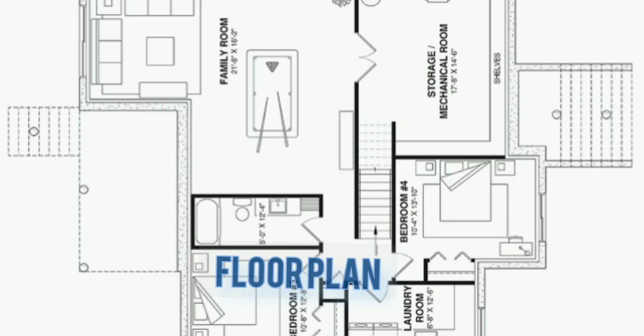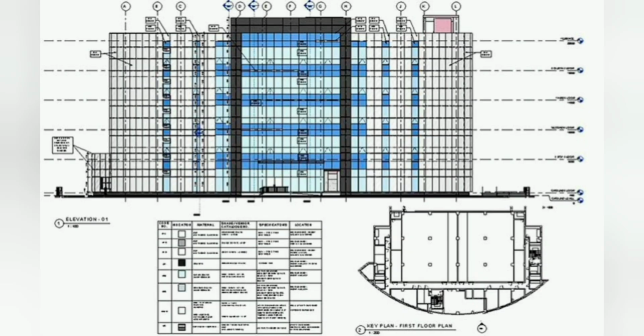These are your primary guide for room layouts, door and window locations, and wall types. Pay extreme attention to the dimensions. Are they to the face of the wall, to the center line, or to the finished surface? This matters immensely for coordination. Next, study the elevations to understand the external finishes and the building's overall form.